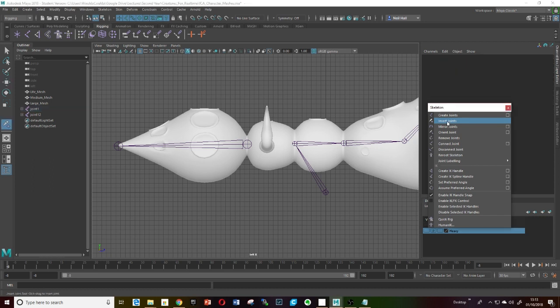If you click on insert joints, what it allows you to do is actually click on a joint, and then if you drag down the direction, it adds a bone. So let's say we want a couple, we can do it that way. And that's added a couple of extra bones into that joint. Perhaps do the same along here. You might want one there as well. Okay.